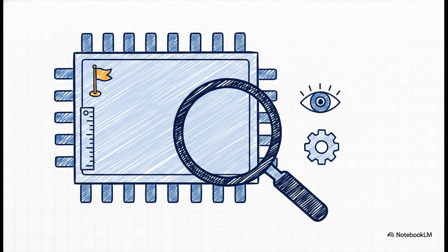Let's check out the precise syntax here. We're defining a region and calling it FLASH. Inside those parentheses, the rx explicitly tells the linker this block has read and execute permissions. Then we lock in its exact physical starting address, the ORIGIN at hex 0x08000000, and its LENGTH as 512 kilobytes. You are literally sketching out the physical chip right there in plain text.